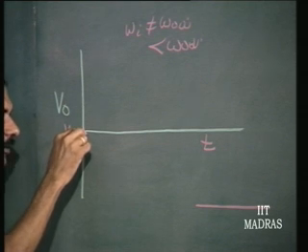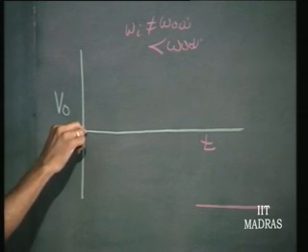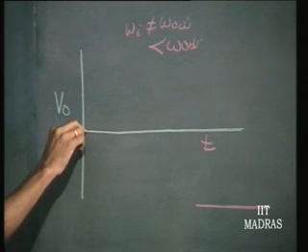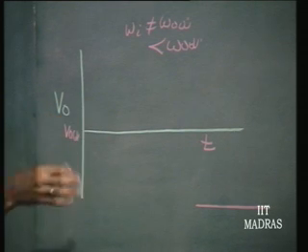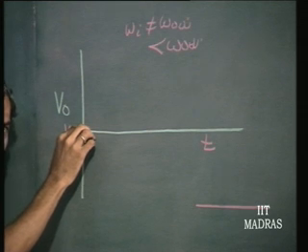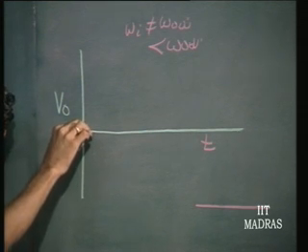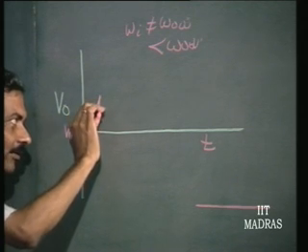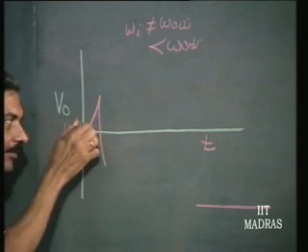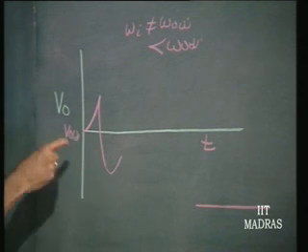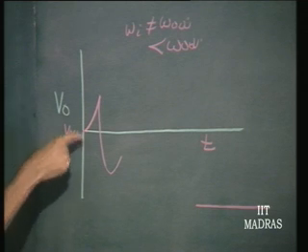Then at the instant of this particular thing, it was equal to omega naught q, and let us say we have produced some kind of sine wave output, because all the harmonics are going to be eliminated by the low pass filter. The fundamental component will have, at every instant of time, frequency changing. Therefore, it is not a sinusoid, but it is something that has a narrow form here and a broadened form here. So, that in effect as a time average it is producing a DC in this direction.